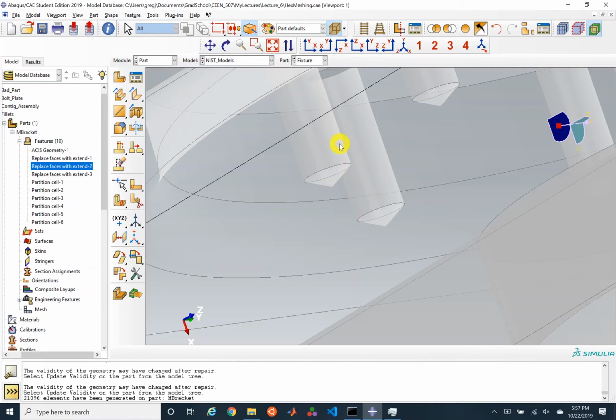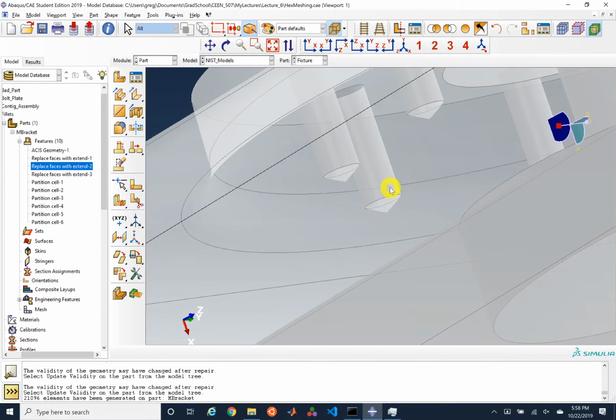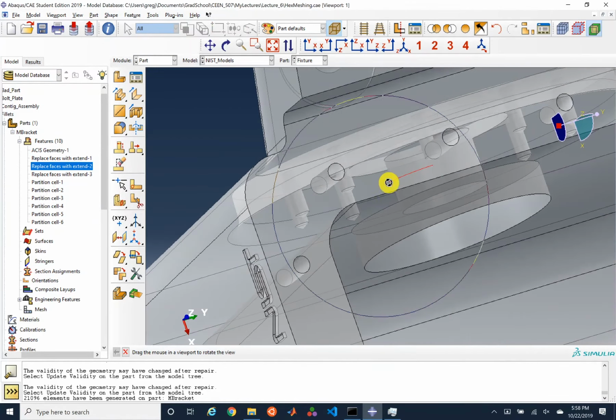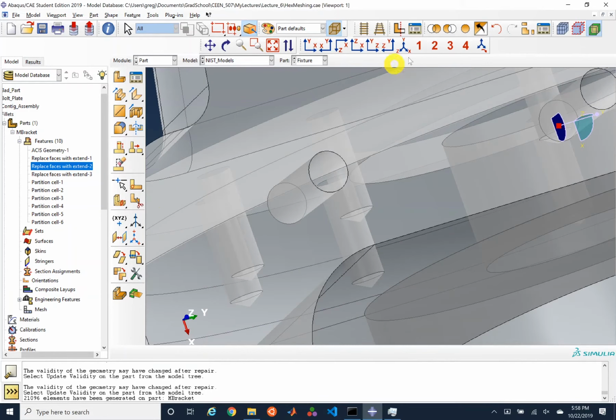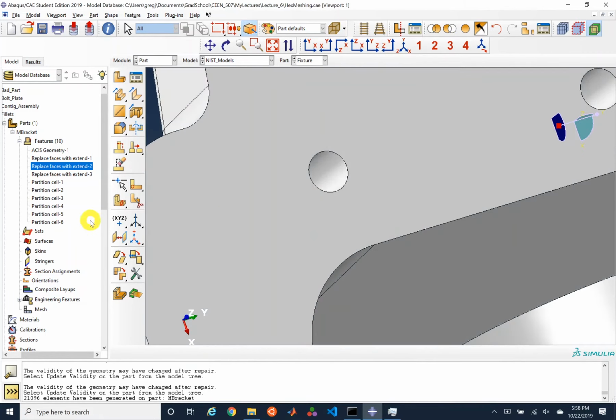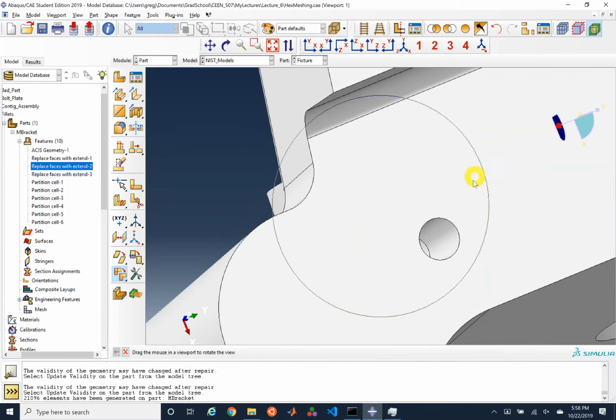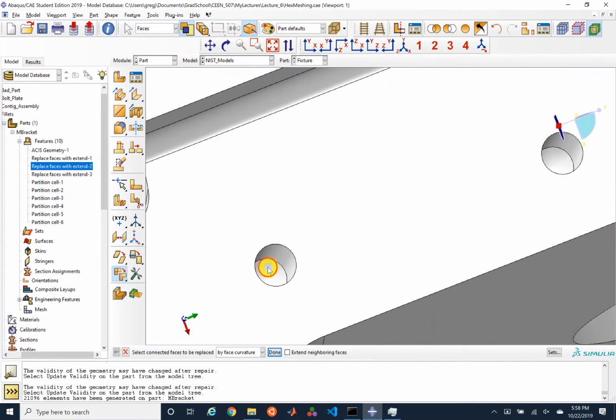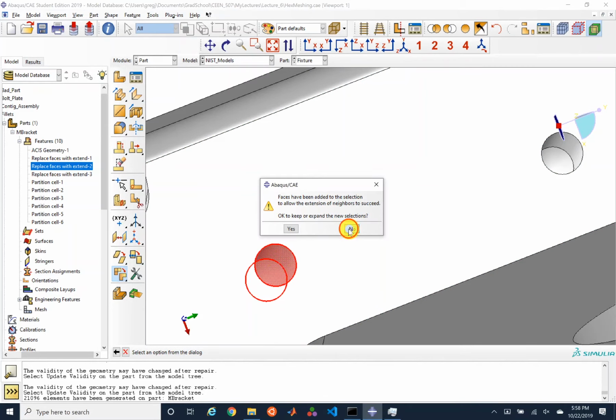And they're really not that accurate to what's actually going to be made anyways. And so usually a very good first step is, even if you want to have these faces involved or these holes involved, you almost never want the conical face at the bottom to be involved. And so you can remove those, usually fairly simply.